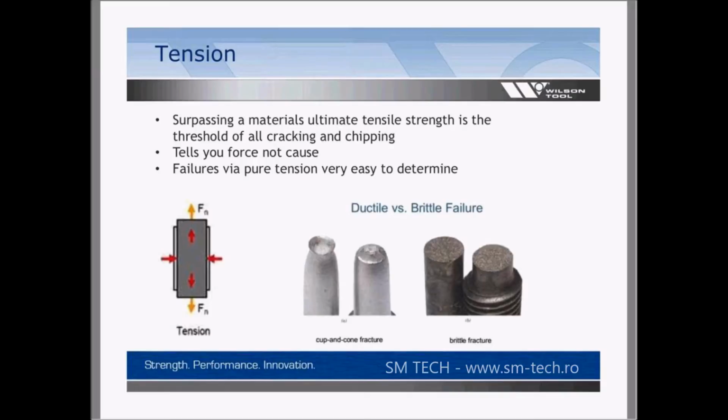Now, ductile failure really is slow acting. They both have their pros and their cons. The slow acting ductile forms show signs along the way. You might see some changes in your product itself before it breaks away. But then again, you might not see that. It's kind of the con. You're going to see small, minor changes because of deformation slowly building up. Eventually, in a tighter tolerance product, you'll start throwing away scrap because of that deformation, and you're not going to be able to see it right away. You have to go back and find the punch and realize that it's expanded a little bit on the cut edge, or a little bit below that quite often.